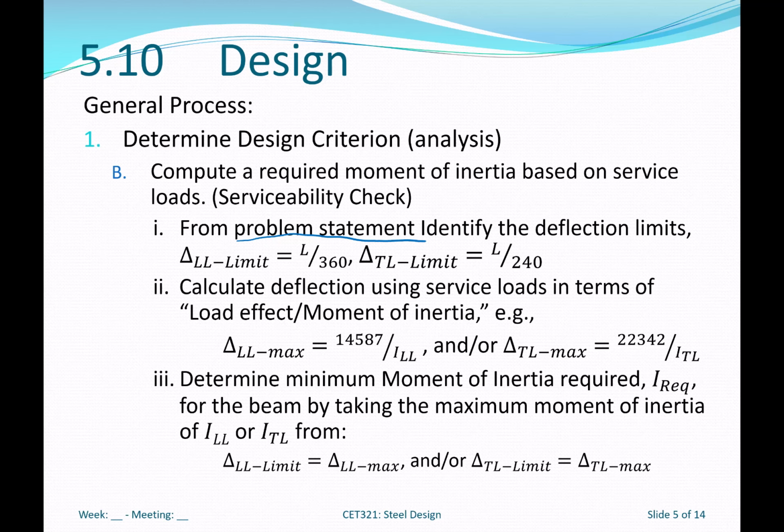But in practice, you need to check strength and serviceability. Okay? So these limits will tell us what our maximum permitted deflection is. And again, in my example a few slides ago, I just said I'm going to assume 0.75 inches for my delta max, whatever it is and whatever it's for. So that gives me my permitted deflection.